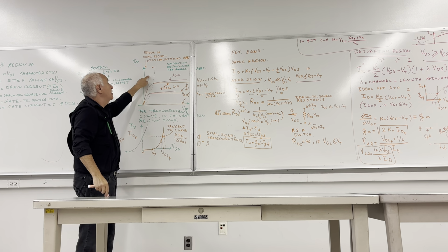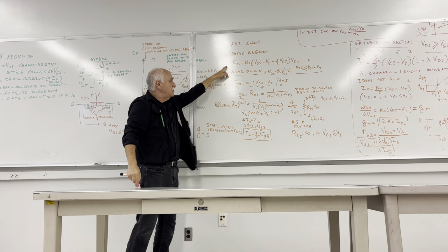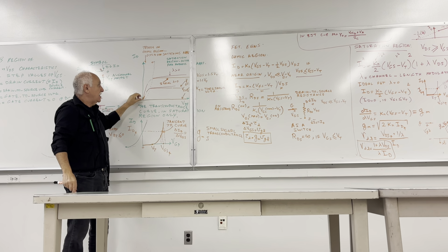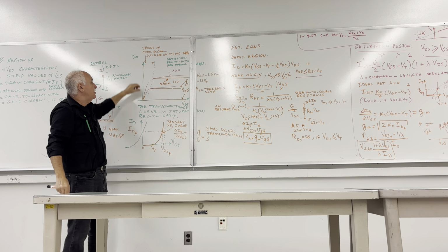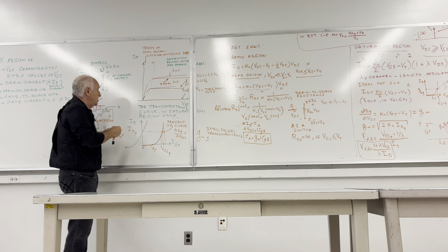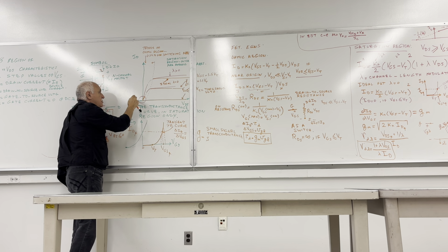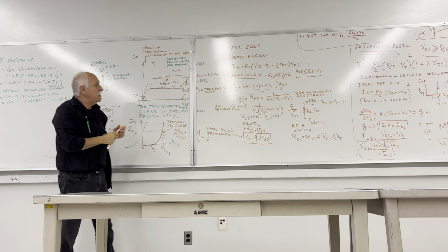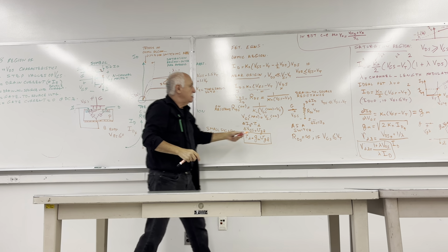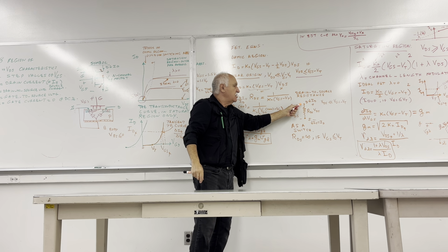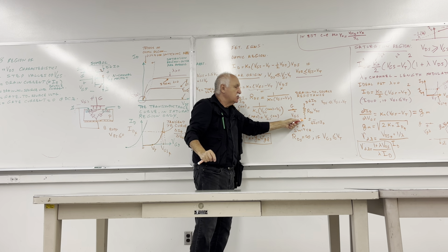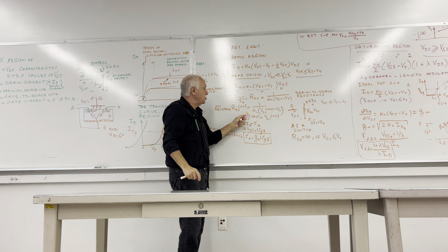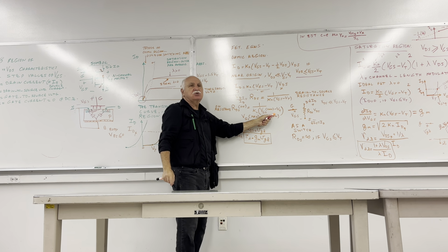Equation-wise, the ohmic region follows those lines. In the origin, which is like deep into the triode region, right there, for switching purposes, then literally MOSFET becomes a resistance between drain and the source, very, very low, that the value of the resistance can be controlled with the gate to source voltage.